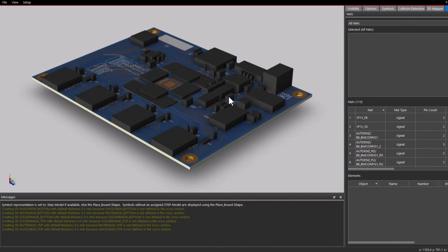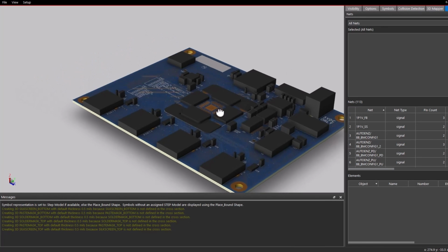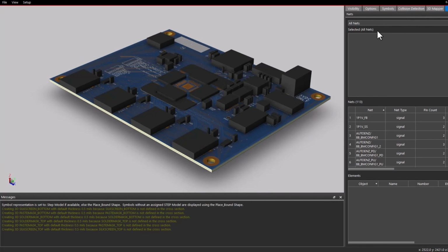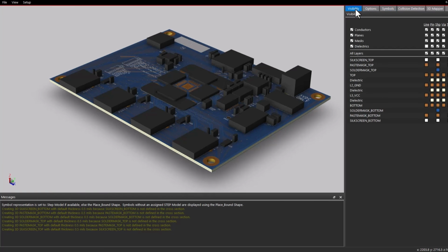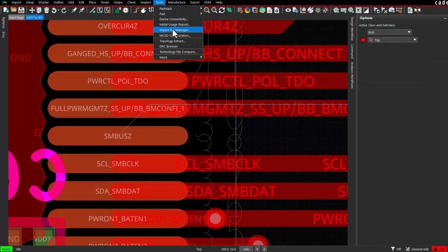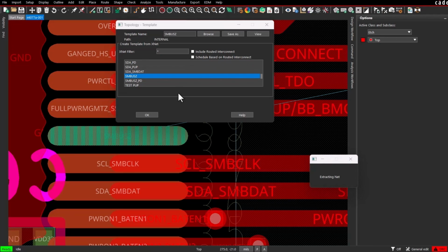Okay, while that process works, finishing your board, exporting it for post-simulation analysis and then updating the board as needed, there is actually a faster, better, more efficient way that I like to call the look-ahead method to signal integrity analysis for PCB design. This is where you pre-simulate your board before you even start routing anything.